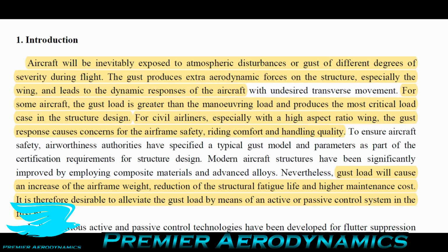The reason why that is because a high aspect ratio wing typically means that the wing is very long and very thin, and that results in a high moment arm. So for those of you who know just basic physics, if you have a bigger moment arm, if you place a load on this moment arm, you then create a greater moment or a greater torque, just simply because you have a greater moment arm, and you can break things much easier. So that's why high aspect ratio wings are particularly susceptible to this kind of phenomenon.